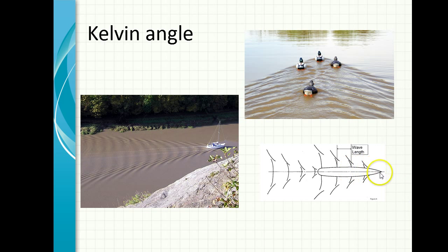So you look here, these are waves which are created by the ship's hull, and there are wavelengths between the crest and the trough. This represents expended energy from the ship. So in olden times, somebody realized that if you put a bulbous bow over here, it creates its own wave, and you design the bulbous bow in such a way that the wave it creates goes and reduces the wave which the ship's hull creates.